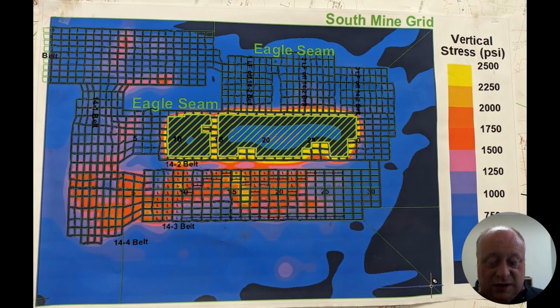And I successfully accomplished that. So we took two separate measurements from these half leaf blocks over here, right? From pressure data within the pillars, I got to watch these pillars fail. The pressure would increase just as you would expect as mining progressed, and then eventually you get to the peak stress, and then of course you get to the strain softening portion of the pillar response, where the stress decreases but the strain is still increasing. You're still having movement, and then you get to a residual load.